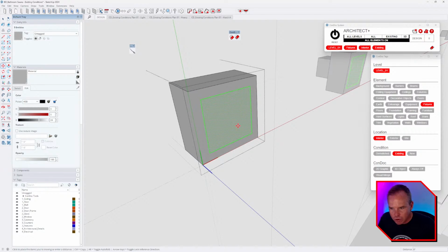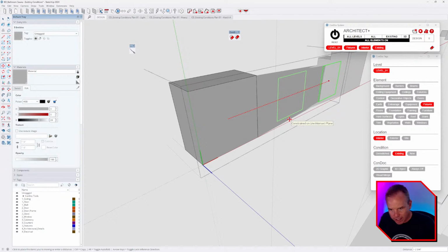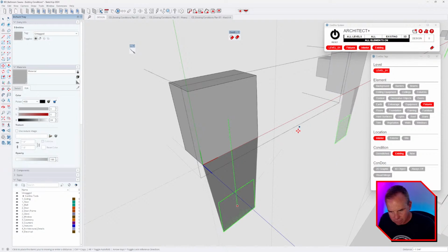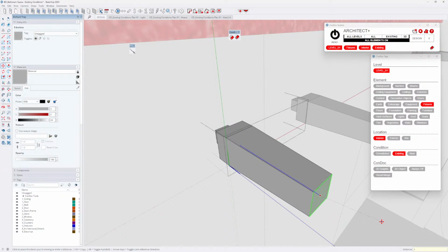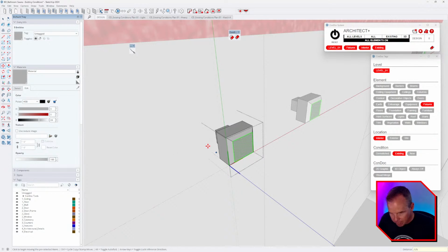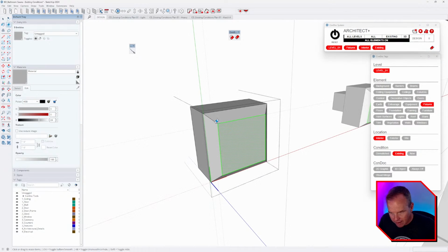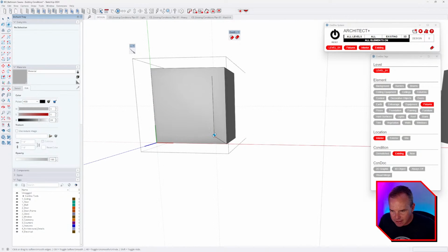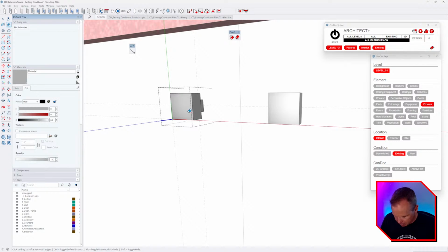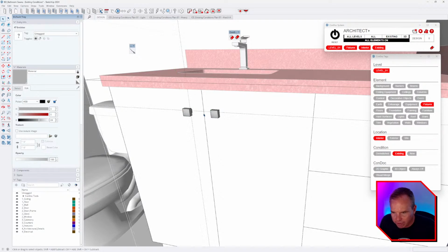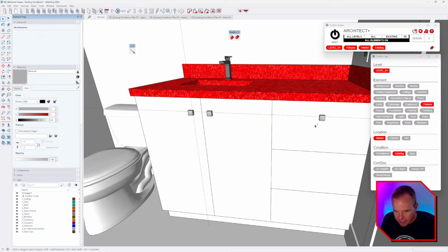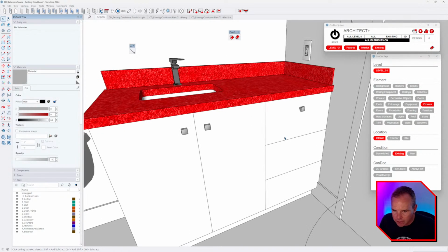And then I'm just going to move it and tap the left arrow, up arrow key, and scoot it out this way by say 0.125, enter. Like that. And when you auto fold like that, then you might even consider softening these edges. I don't necessarily want that line work to show up. It would be pretty heavy in elevation, but that might soften it for a rendering if we go that far. Control E is my keyboard shortcut to clear my guides.